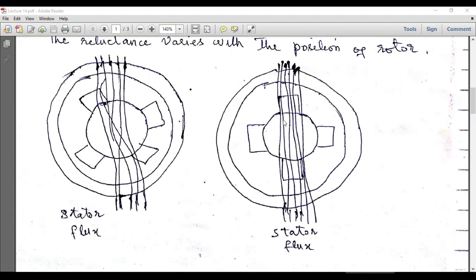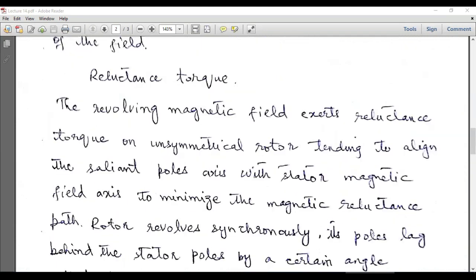The only problem with this motor is that when it is running, there are unequal air gaps between the stator and the rotor. Due to these air gaps, this motor will offer jerks and noise, and there will be air friction when these salient poles cut away the air pockets between the rotor and the stator. Due to this, there will be jerks in the rotor and noisy operation.